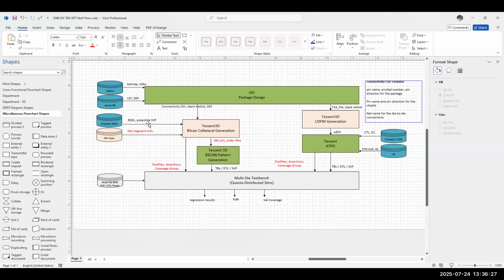So maybe you can create a little snippet of what would be in that section of the TDK. Create a very simple chiplet, and then a little cartoon of the chiplet that shows the IOs, the test pins, and how that information would be captured in the TDK format. Yeah. We only have access to the pins, so the micro bumps for a standard chiplet, or hybrid bond for a hybrid bonding type of device.